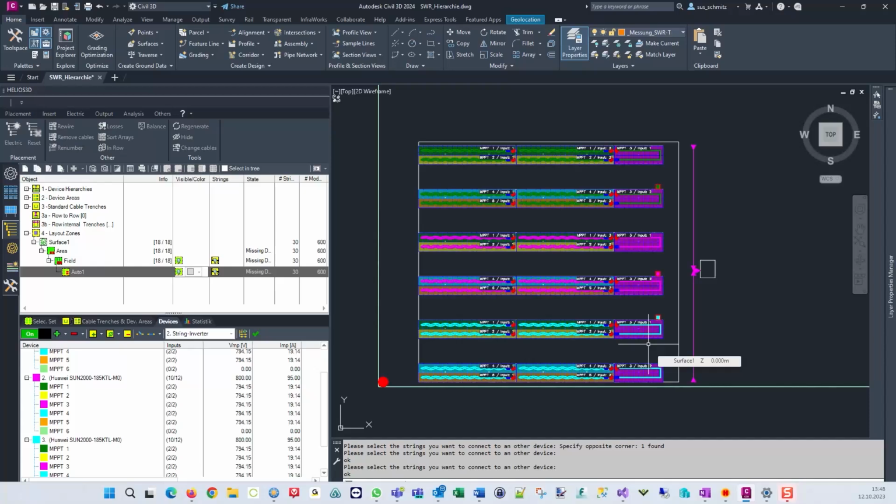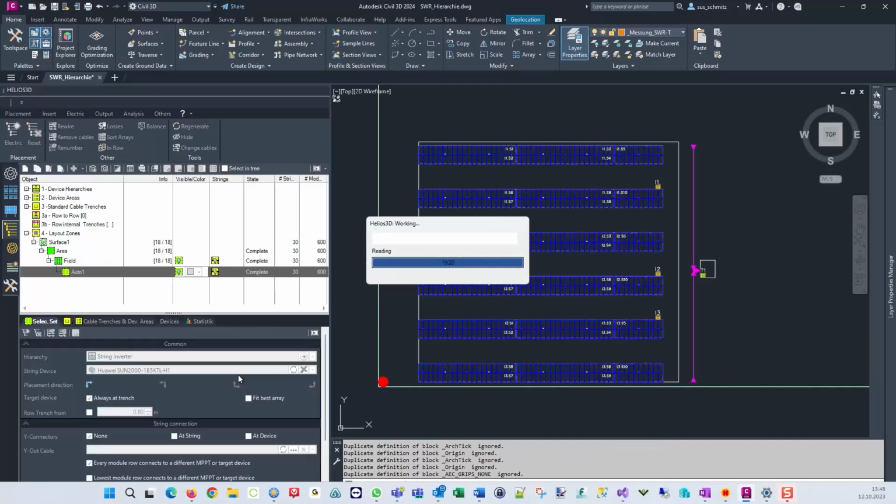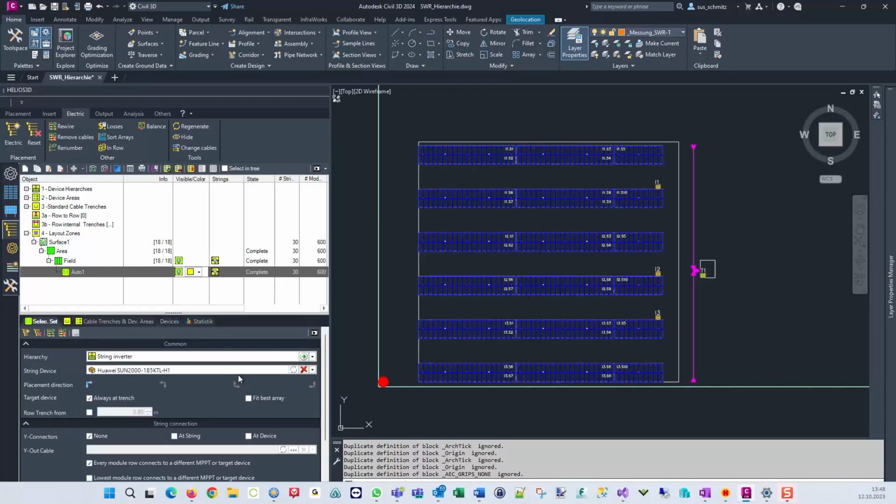At this point we can go to the next hierarchy level and add our transformers manually as well. On the other hand, for central devices, we expect the auto-completion to be the usual choice. To auto-complete, we just click at the green hook. After auto-completion, all devices up to the grid got added and the manual edit mode was ended.